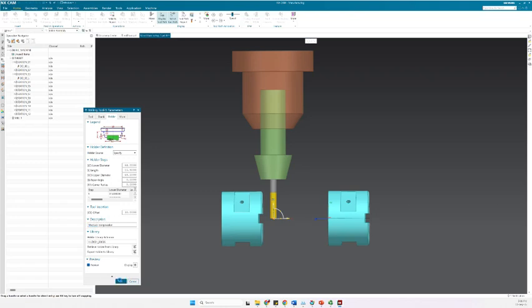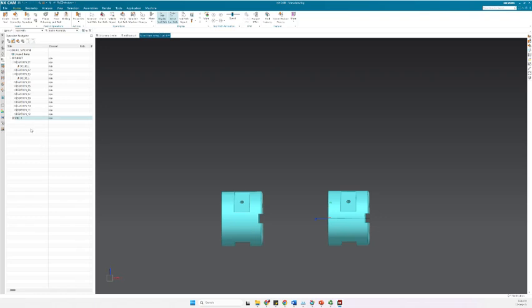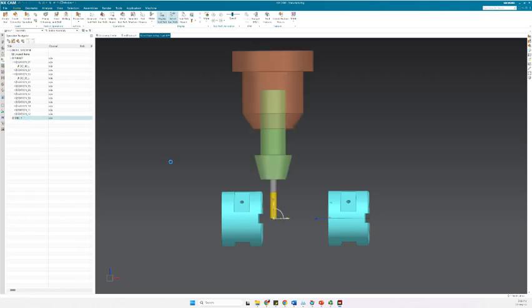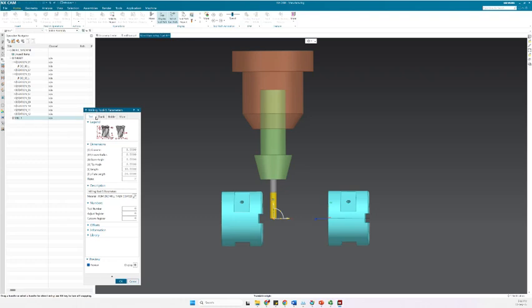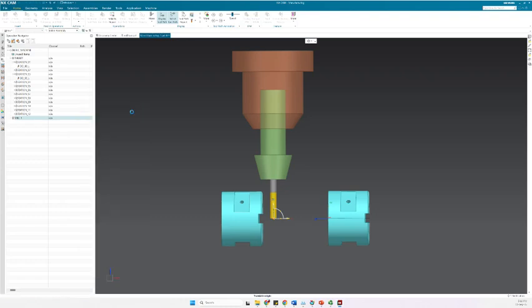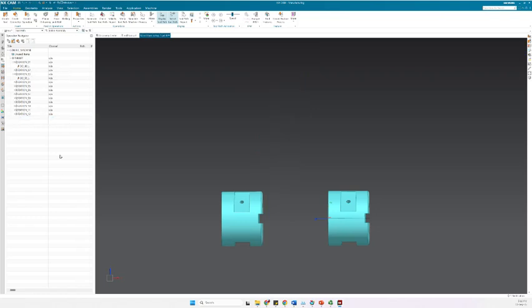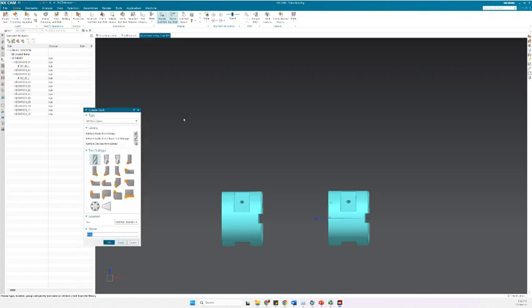And let's click OK. So this is my tool, or actually I have also forgotten to define it in a correct tool station. Let me define it again. So now you can see that I forgot to put it in a specific station and it's out of the turret, which is not good. I will just create a tool again here, and here is the one that I missed. I put it in mill 1.